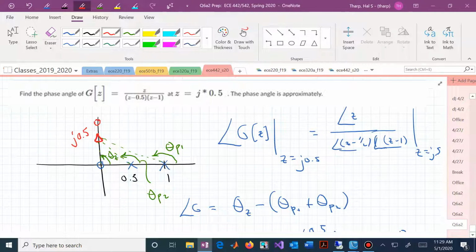So you could see that you could numerically evaluate any particular location. If somebody now said, I want to know where the root locus intersects this dashed vertical line, you could now start looking. I mean, you wouldn't really want to do this, but this is to give you insight. You would just plot this in MATLAB to see the root locus, but now you would say, the angle at this point was, let's say, minus 195.